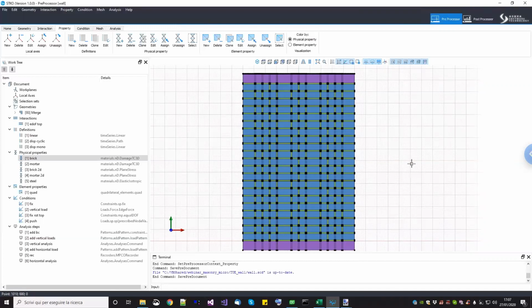So if you downloaded STKO plus OpenSees, the OpenSees version that you have there has an additional constitutive model for concrete and masonry that is quite effective and quite robust, because it uses a particular integration algorithm that basically makes the model almost always converge.